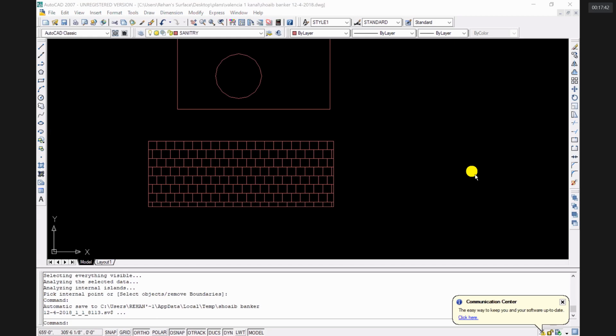Mostly, if you have to change the lintel level, you can change the lintel height of the main entrance door. Otherwise, lintel level is the same, either 7 feet or 8 feet, depending upon the size of the building. In our department, throughout the building, the lintel height is 10 feet. The sill level can be changed.